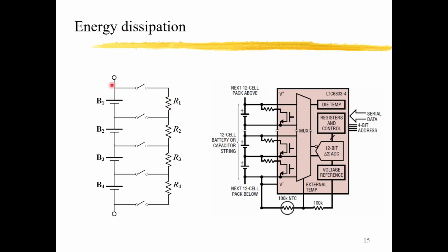And you know, when the SOC of some cell is higher, we can also expect the voltage of the cell to be higher, right? So if we just simply put each cell in parallel with the same resistor, then if the cell's SOC is higher, the cell will dissipate more energy on the resistor because the voltage is higher.